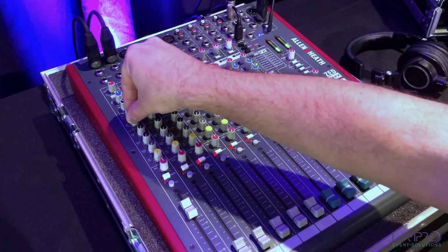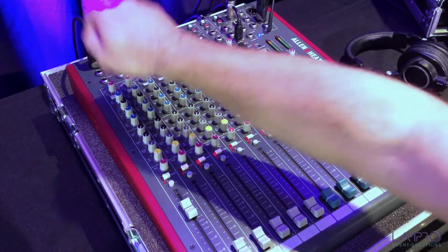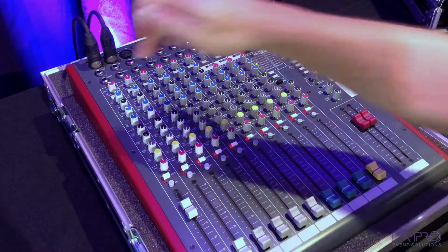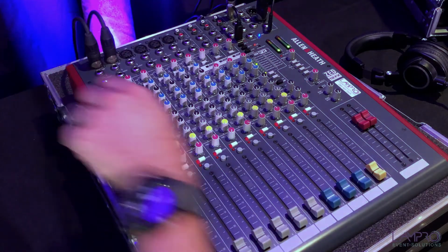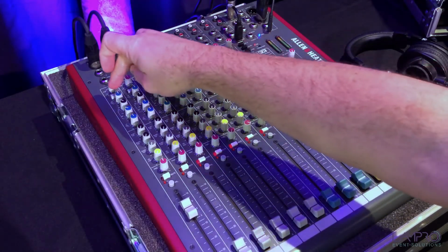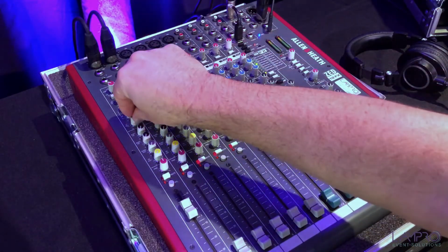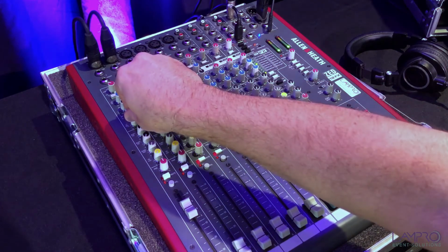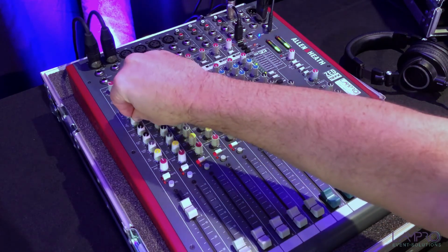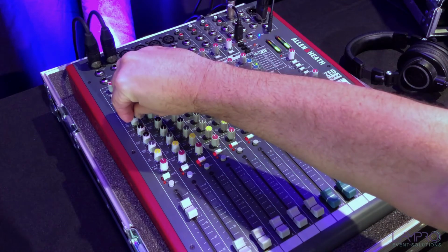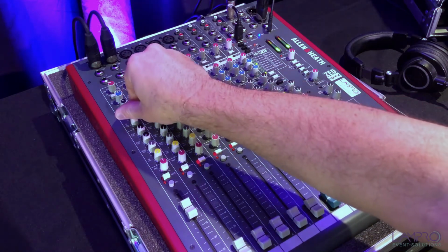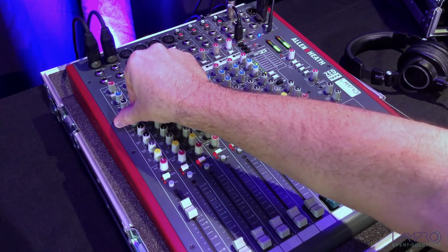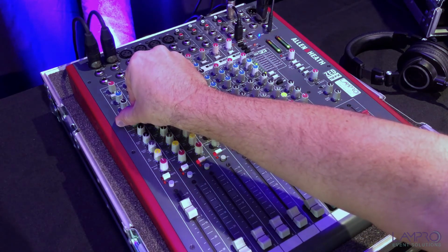But because I'm using the 100 hertz switch at the top there, the high pass filter will cut all the low frequencies below 100 hertz. So maybe let me just undo the 100 hertz high pass filter. And if I adjust the low frequencies now, you'll hear it sound a lot tinnier or a lot thinner. But if I boost the bass or boost the low frequencies, you'll hear a lot more of those low frequencies coming through.